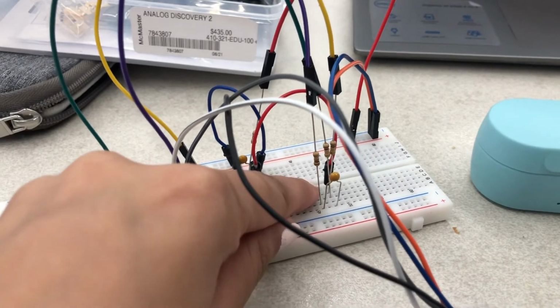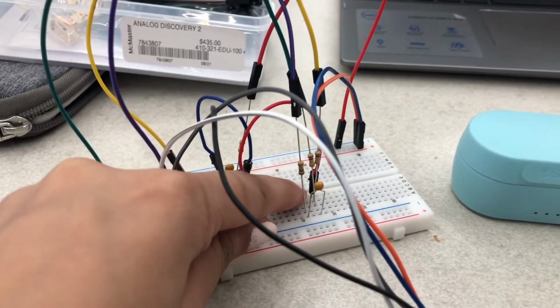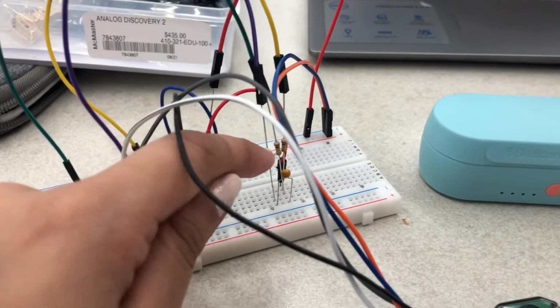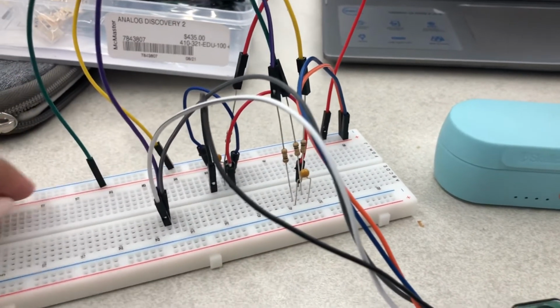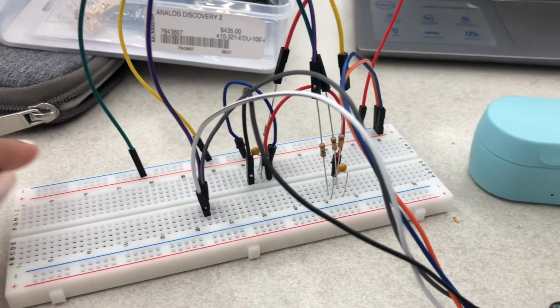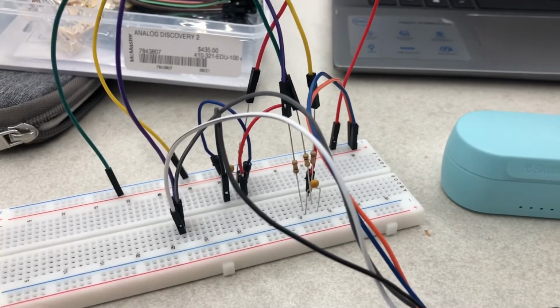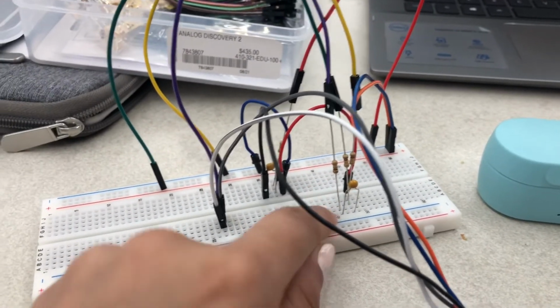Lastly, the base of the BJT is connected to this red wire, which is then moved over to this side over here. From this red wire, where there's much more space, you can see that there are 2 100K resistors. Both of them each go to a positive 5 volts and a negative 5 volts that was mentioned earlier, which is also shown on my schematic.